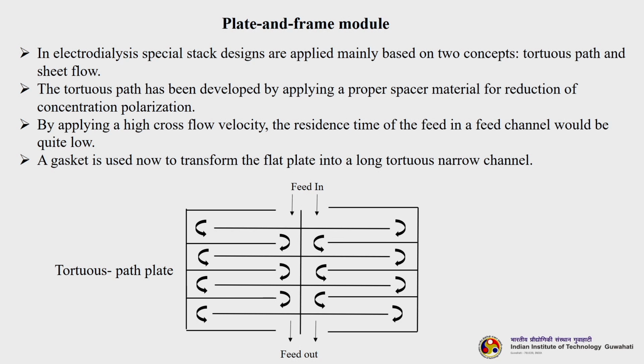In electrodialysis, special stack designs are applied mainly based on two concepts. One is the tortuous path and another is sheet flow. The tortuous path has been developed by applying a proper spacer material for reduction of concentration polarization. The aim of developing this tortuous path is to reduce concentration polarization, so as to minimize fouling. By applying a high cross flow velocity, the residence time of the feed in the feed channel would be quite low. A gasket is used to transform the flat plate into a long tortuous narrow channel.